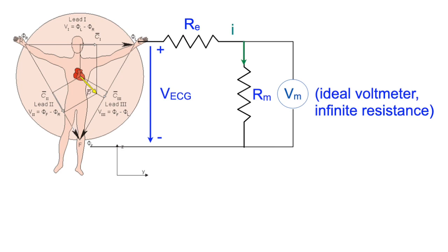So what's that? On the right hand side you see this circle with a V in it. That's a voltmeter. It's a symbol for a voltmeter. It measures volts, obviously, but it's an ideal voltmeter. So it's perfect. But of course nothing's perfect. So what does a non-perfect device look like? Well, it looks like a perfect device in parallel with a resistance, which we're calling the measurement or RM resistance. So the two of those things together form a schematic representation of a real voltmeter. Okay? So that's the circuit we're dealing with.